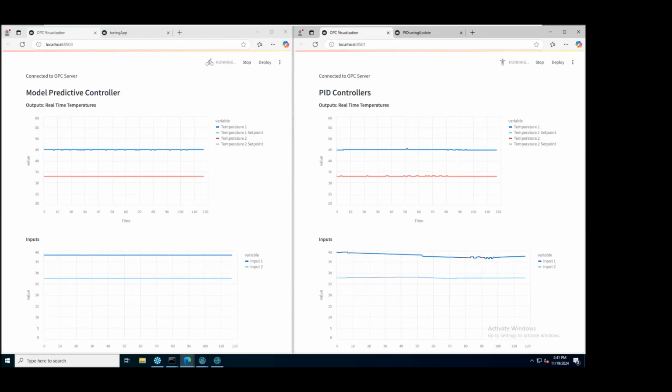And secondly, as the name MPC or model predictive control suggests, we use a model to predict how each of these input variables affects every single output variable. And this means that the interaction between input variables is inherently accounted for, which is something that PID control does not do, right? Since it is a single input, single output control strategy.